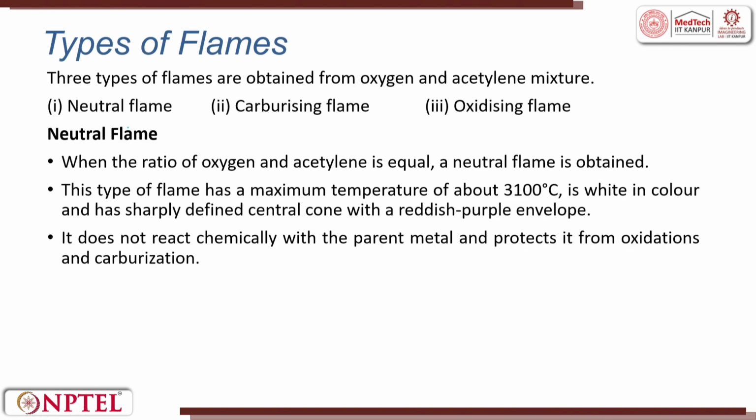So, there are three types of flames: the neutral flame, the carburizing flame and the oxidizing flame. Why are these important? Because the heat which gets generated differs for each. How do you make the flame neutral, carburizing or oxidizing? Based upon the compositional difference between the two gases. Neutral flame: when the ratio of oxygen and acetylene is equal, the neutral flame is obtained.